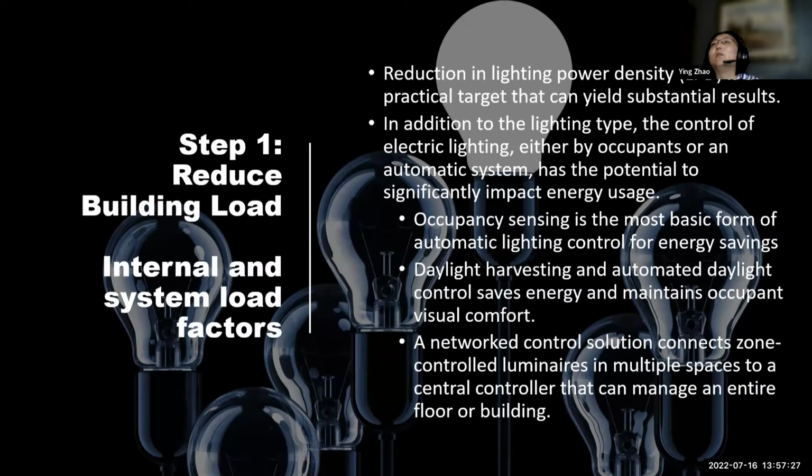If it's in heating mode, it reduces the set points, or in cooling mode, it increases the set points, so that will use less energy. Or it reduces the supply air, or reduces the ventilation, something like that, to reduce the energy. So that's synchronization between systems for a more centralized control.